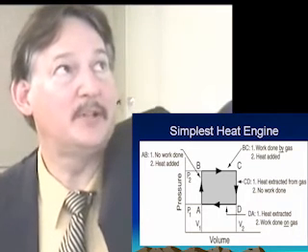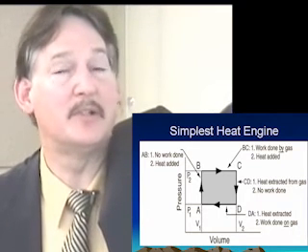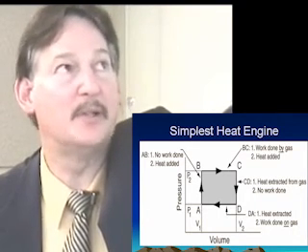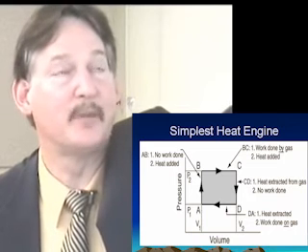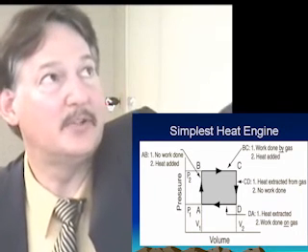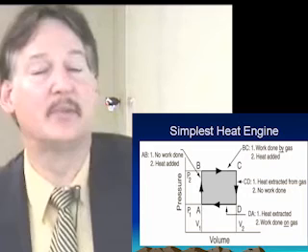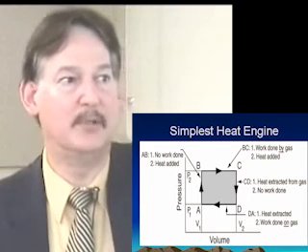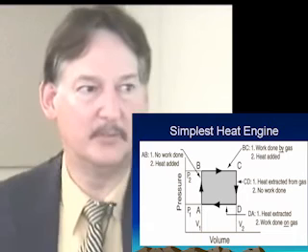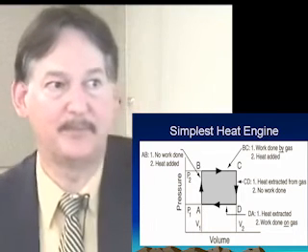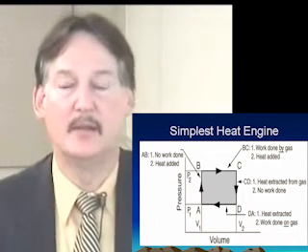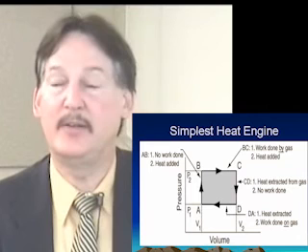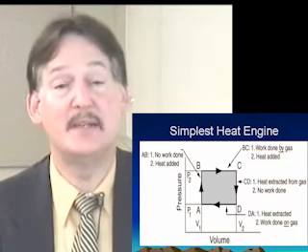Now, once we get to point B, knowing the pressure at B and the volume correspondingly, we can find the temperature. And we can transition from B to C. And notice that as we go from volume 1 at point B to volume 2 at point C, there is an area underneath that line BC.